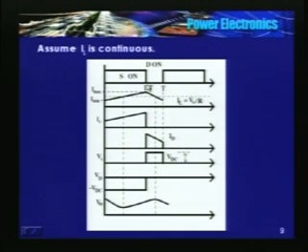The moment I turn off S, D is turned on, because the inductor current has to be continuous. That current starts flowing through the diode D. So, this is the diode current variation. It jumps to I max, falls linearly, and at T you switch on S again.